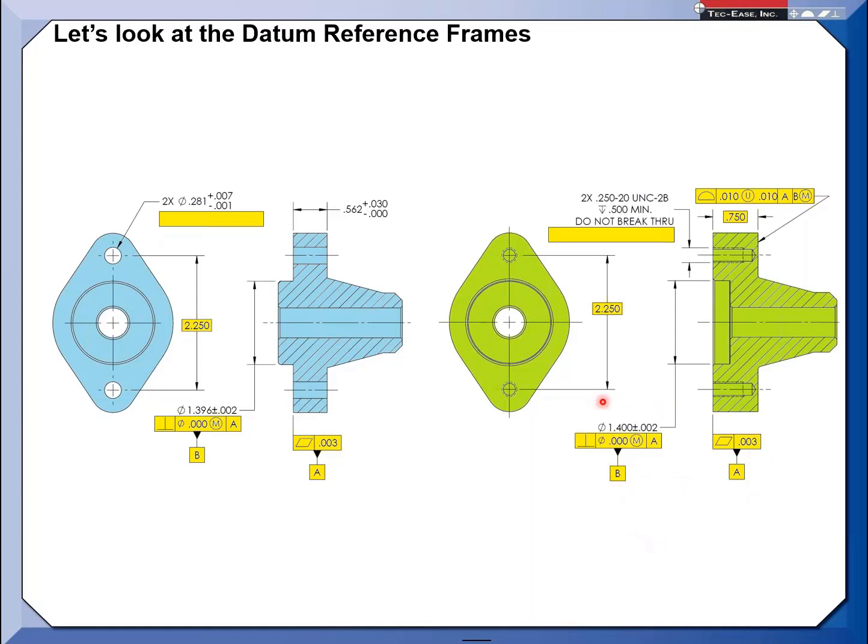And then same thing here, the hole is relative to datum feature A. And again, this becomes a secondary. So on both these parts, we're going to derive a datum axis in a relationship to the primary plane. And then up here, same thing. What do we do, and what should be up here in the feature control frame dealing with a threaded blind hole? And on this one, we've got a clearance hole, and that's where you're going to look at this as a complete picture of a mechanical joint.